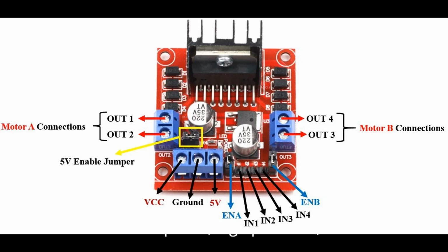Advantages. Faster response, high precision, and better control under high dynamic loads. It also reduces the need for speed sensors, making the system more robust. Applications. High-performance applications where precise control and rapid acceleration/deceleration are needed, such as in robotics, electric vehicles, EVs, and high-speed machinery. Examples. High-end VFDs from manufacturers like Siemens, Dynamics S120, ABB, ACS 880.